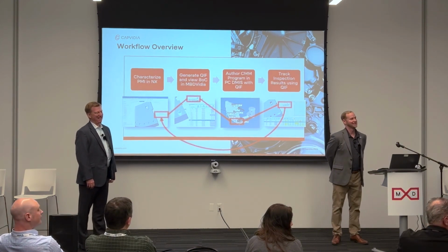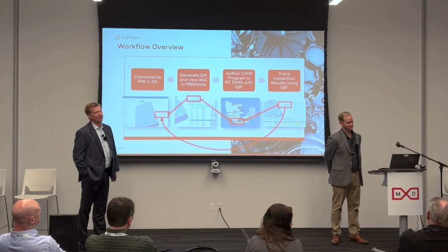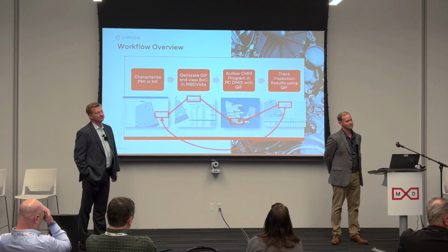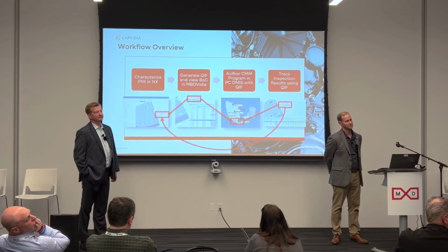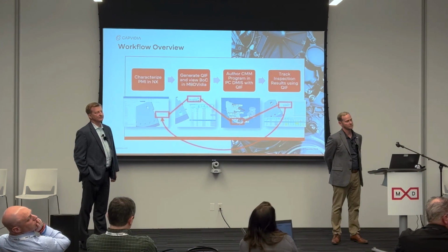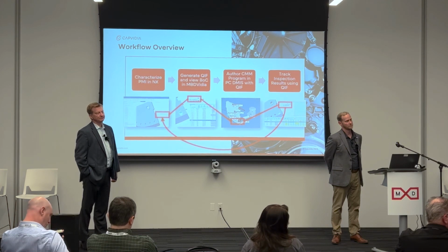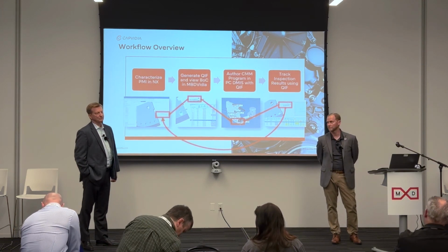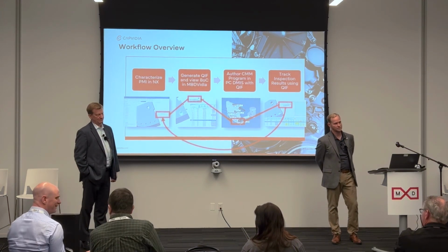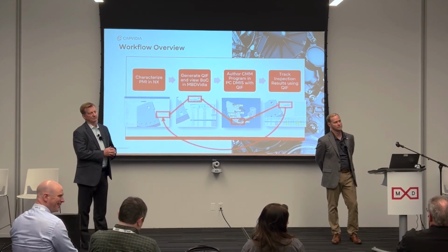Excellent. Curtis made the point that the two big things in QIF are features and characteristics. It's not clear exactly how you're planning to use features here. What you could do, and maybe what you're planning to do, is have an other shape characteristic associated with a bunch of CAD faces. But in order to do that, presumably your PMI must be associated with a group of CAD faces in the first place. Do you have specific plans for carrying through and using QIF features?